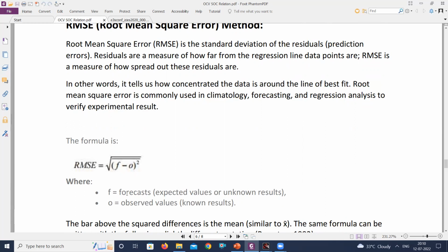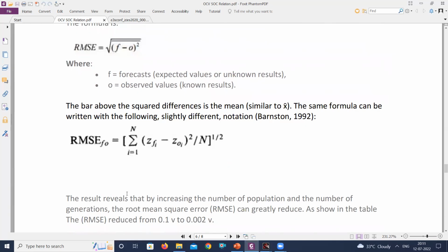If you have fewer data points, you will observe a higher error, because there is less averaging. The more data points you have, the more the averaging increases and the lower the error you observe. So if I am correlating this correctly, then in BMS this function should be accurate enough. Otherwise, exactly what you told earlier, it might give the wrong indication and you are not utilizing the full capacity. Yeah, if you are correlating the internal resistance with the OCV, that is the true reason for it.